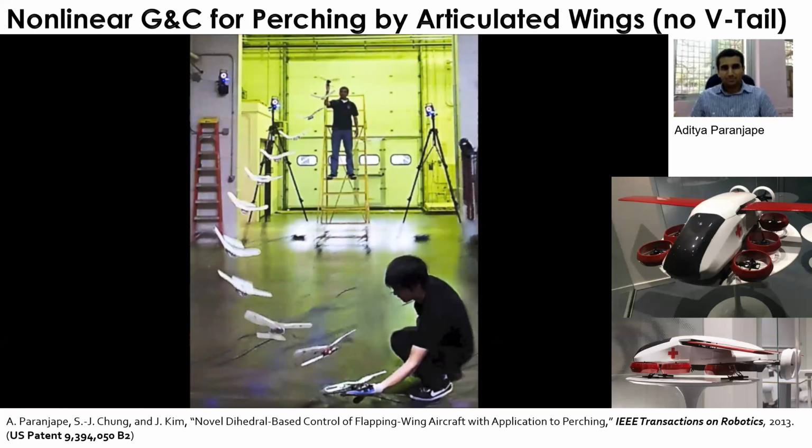So how are you going to solve this complicated optimal control problem to find the optimal path in the presence of stochastic uncertainty? What's new here is that we have a CDC paper called trajectory optimization for chance constraint nonlinear stochastic systems, and a recent extension where we combine this method with learning is going to appear in Robotics and Automation Letters. The idea is that you can turn this nonlinear stochastic differential equation into a deterministic equation using polynomial chaos approximation.